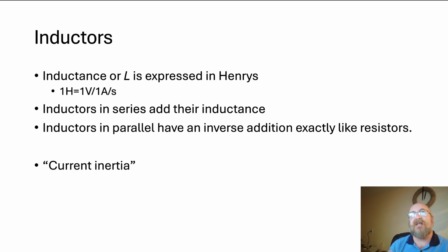It's important to realize that this is about how fast we change the current, how many volts we're going to get. That's why there's that per second there. Inductors in series add their inductance just like resistors, and inductors in parallel have an inverse addition exactly like resistors. So we deal with inductors the same way as resistors, whereas capacitors are the exact opposite.